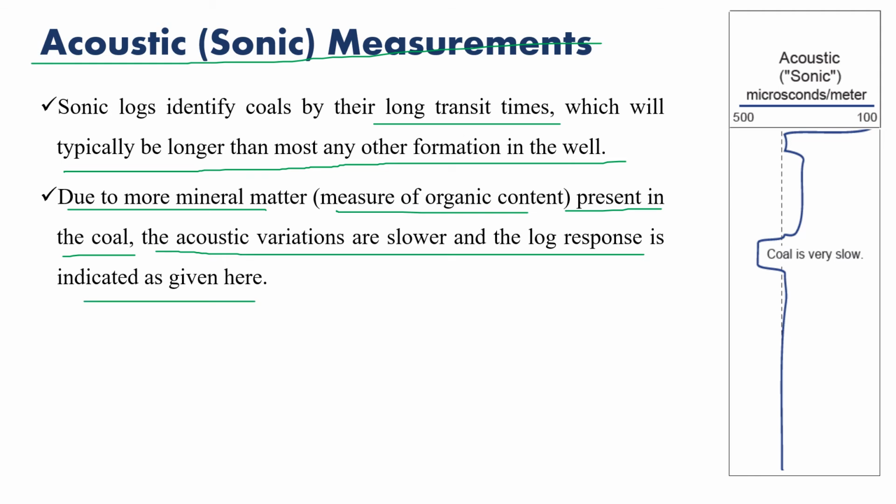So you can see coal has a long transit time, so it has a very low sonic measurement. See, it is taking 500 microsecond per meter. Okay, so the acoustic log interpretation is on this side, from right to left.